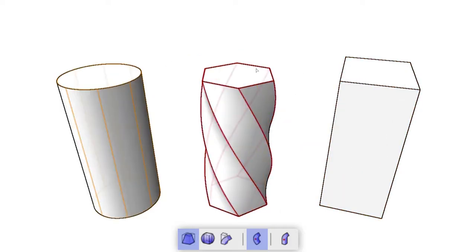A four-way arrow graphic will appear, indicating that the object will be tapered in all directions. The location you place the UI element determines where the selected object will be tapered to. The next click will determine the sensitivity of the taper operation. For instance, if we don't click far from the four-way arrow element, the taper changes dramatically with just small movements.